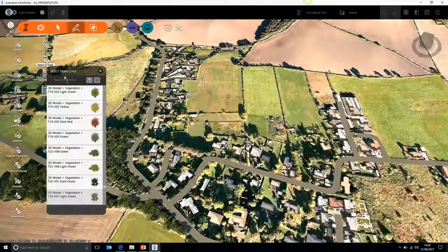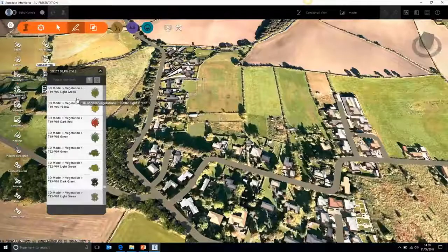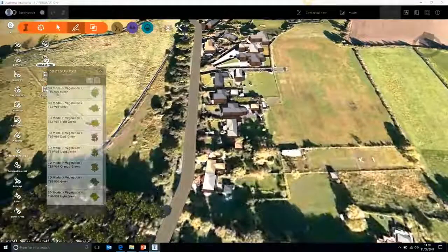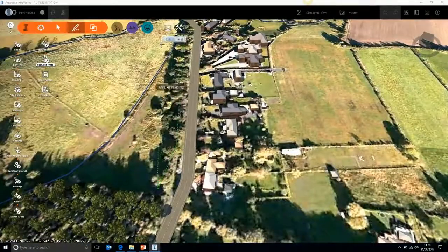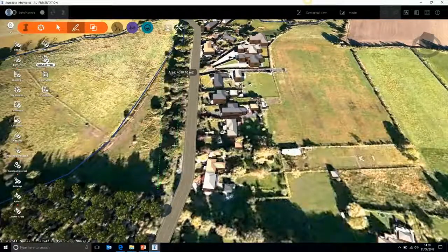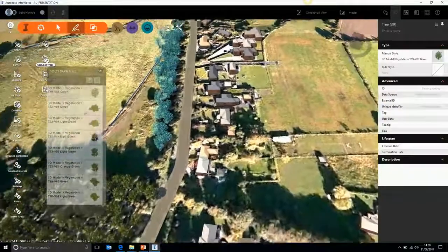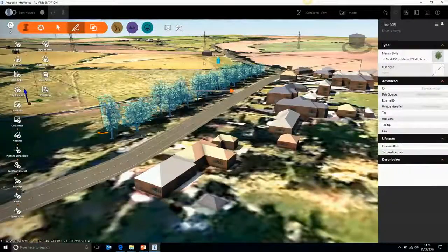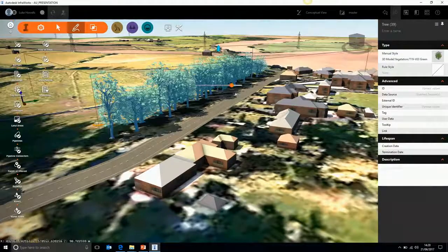So, as I said, we have a selection of trees we can bring in. We can bring these in one by one, or we can bring them in as a multitude of rows. Those of you who are most familiar with InfraWorks will probably have used the point of interest feature before. It's just a case of tracing over where we have them before. Put it in, and flick around. And then you get all the multitude of controls, and when we click on them we can change the height, the progression, the actual foliage rates. So we can get a build-up of the sites we've got in here.